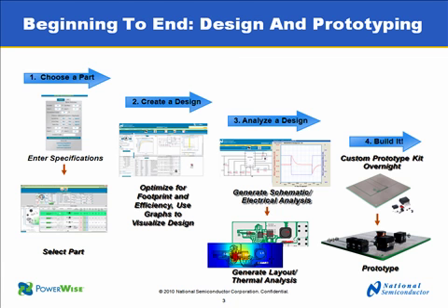WEBENCH is actually a four-step process, beginning to end. First, you choose a part by entering your specifications for your design. You're normally presented with a listing of options for different parts that you can use in your power supply. The second step, you create the design, and here the BOM is created, including all the passive components and other things that are required to make the thing actually work.